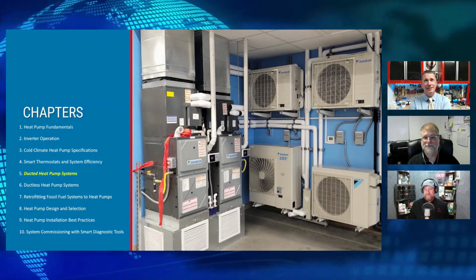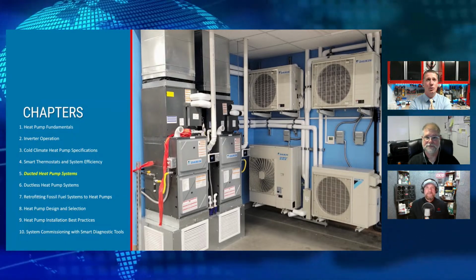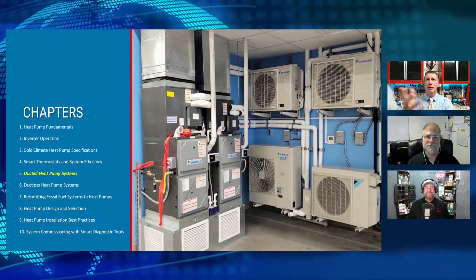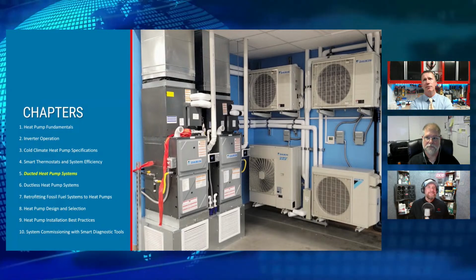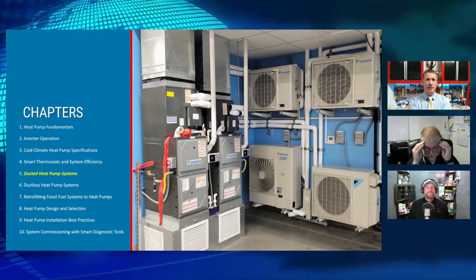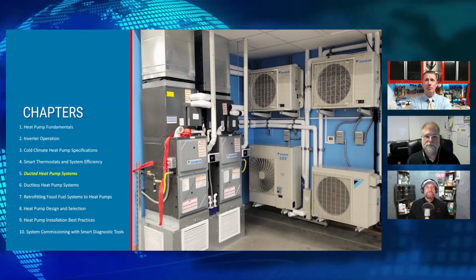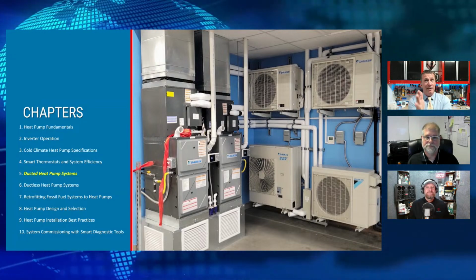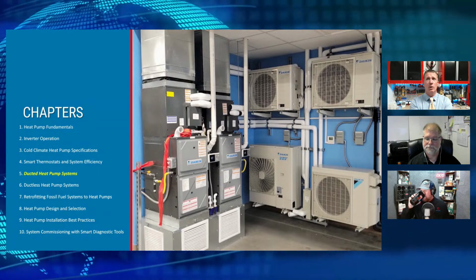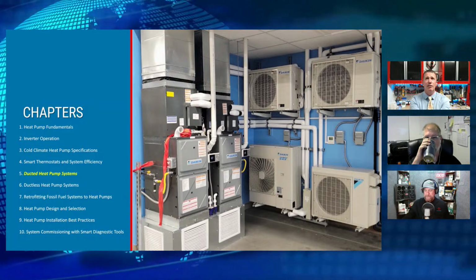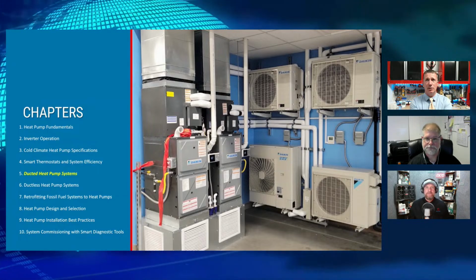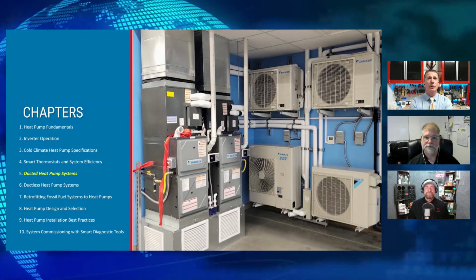As we start getting into some of these more advanced pieces of machinery, it is so critical, especially when we talk about things like airflow, right? So here's an example of some equipment. This was from one of the facilities that we've visited here recently. When we start talking about inverter installations and the changes of motors, if you haven't realized, we've already moved away from PSC motors into ECM motors for the majority of our indoor units. So we've replaced them with higher efficiency motors. I cannot get the performance out of an inverter, particularly if I have not started with proper airflow.